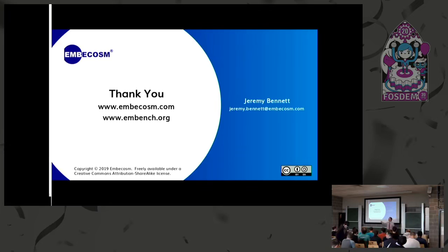Actually, I'll take this one over here. So you say you tested it on real hardware? But there are obviously differences between chips, because some might have speculative execution, some might not. So these benchmark numbers you showed for the performance, what's the reference platform used there? So the question is, what is the reference platform used for Embench? Because reference platforms are implemented by the hardware implementation. It is the RI5CY Risky core from the Pulp project at ETH Zurich, and that's an open implementation, and it is a specific commit from their GitHub repository of the Verilog source.